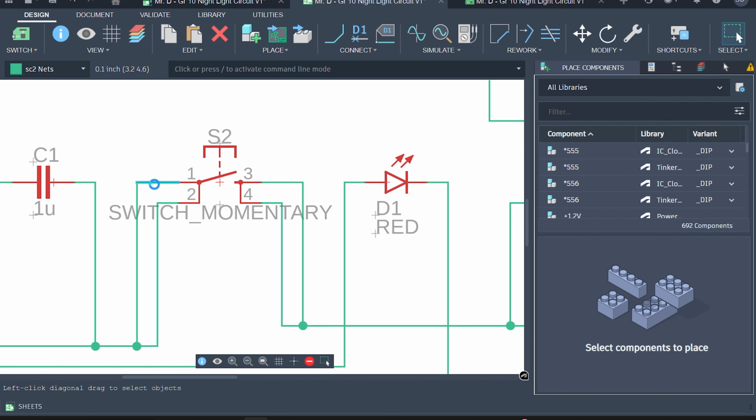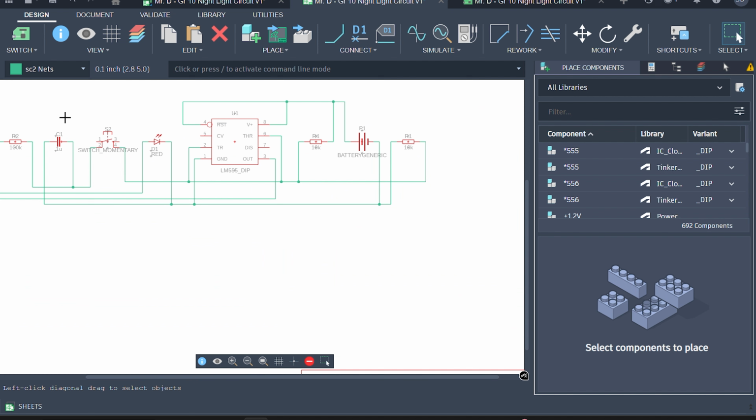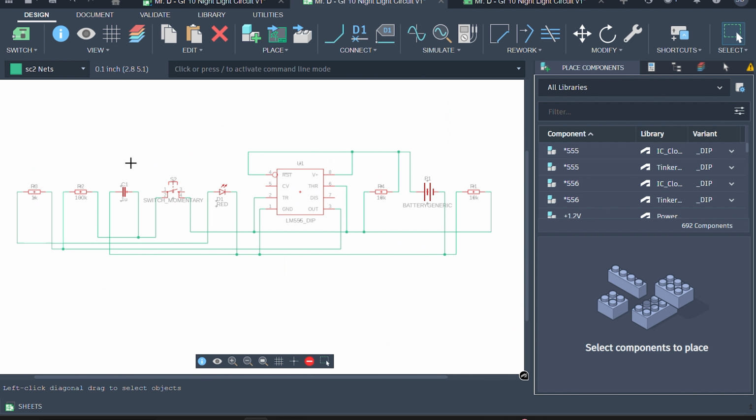So what we're going to do to make it easier for us in the next step is we're just going to make it so we only have 1 connection to each terminal. And the reason we do this is because in the next step we actually have to route where on our physical circuit board we want all these connections to be made. So basically we're just getting rid of any extra connections so that there's less for us to what is called route, saving us space on our circuit board.